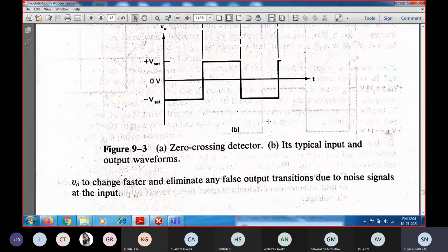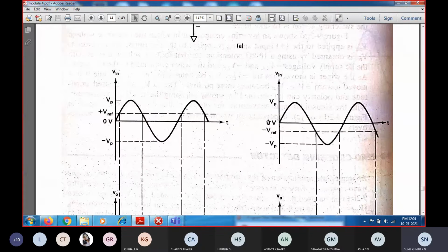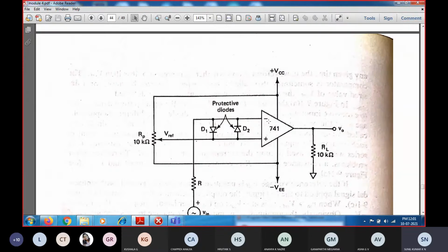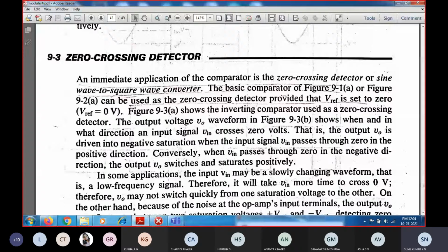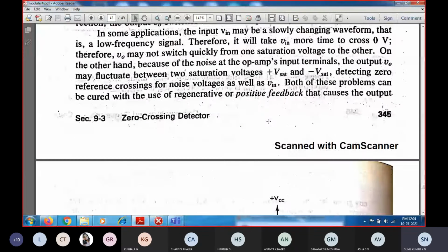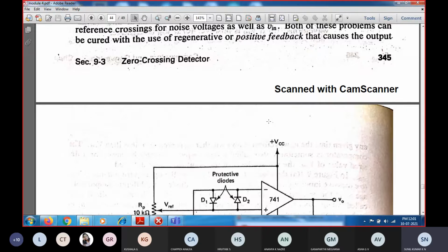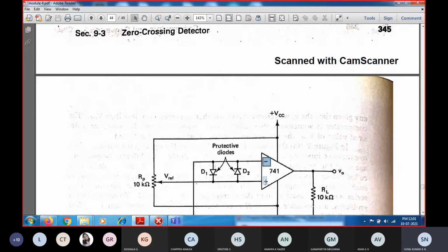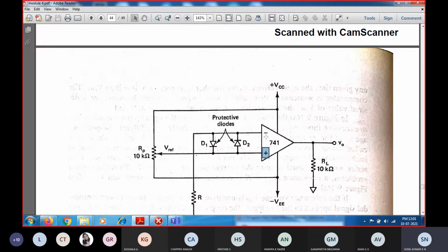So among the two input terminals, inverting and non-inverting, suppose the non-inverting input voltage is greater than the inverting input voltage, just by 30 microvolts, as I mentioned earlier. If there is any voltage difference of just 30 microvolts in a direction, whichever is larger will make the output saturate in that particular direction. If the non-inverting input voltage is greater than the inverting input, since we have not employed any feedback, the basic op-amp circuit is going to work like a comparator circuit.